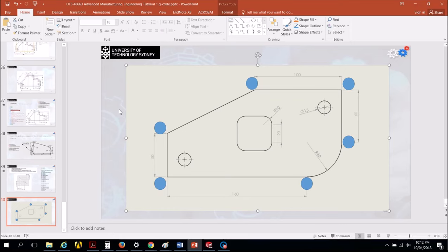Now the most common thing, if I'm going to have small dimensions like this one, where the longest length is going to be 200 millimeters, and the furthest height is going to be something about 100 millimeters. So the best thing is to hold it with the vise. If I'm going to hold this part with the vise, I will not be able to do the profile cutting. Even if I'm going to use the clamp, I will not be able to do the profile cutting, simply because the cutting tool is going to be cutting the clamp device.